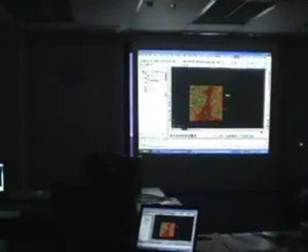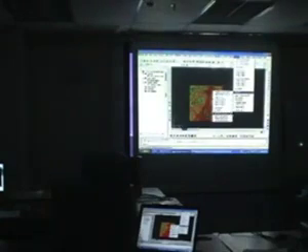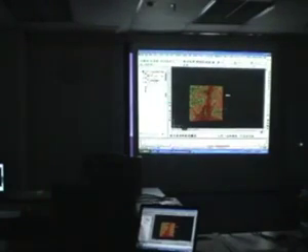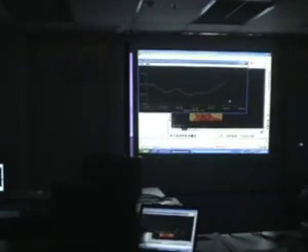Okay, just to cover a bit more about Land Desktop. This is another very unique feature that's been around since Land Desktop 3. Let's say I just draw a polyline right through. I don't even have to draw it as a completely straight line. I'm just going to draw it as a line that goes through. And I'm going to use sections. This is, let's say, if I want to view a profile of the terrain. I'm just going to click this line. You can see the profile immediately.